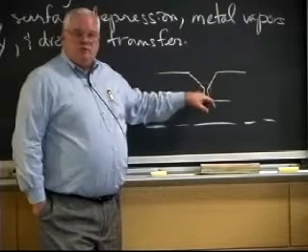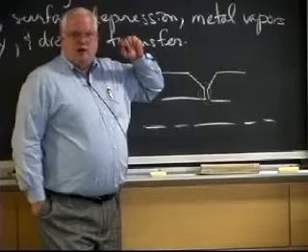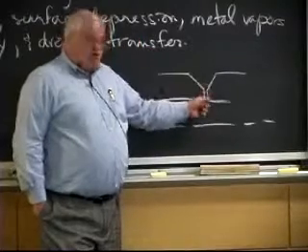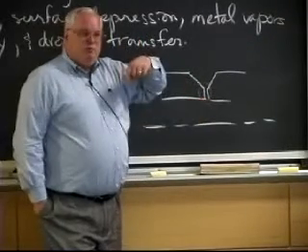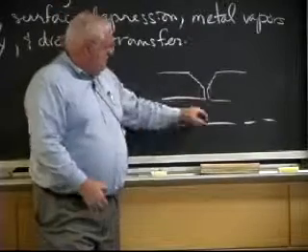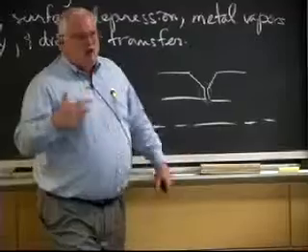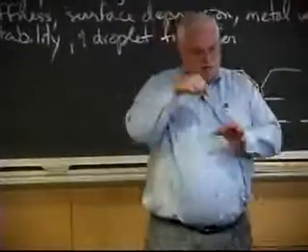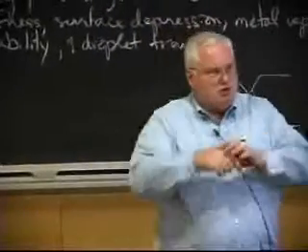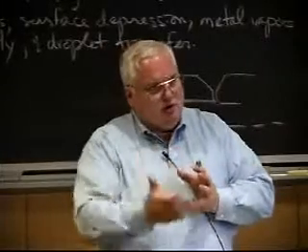The reason is that the root pass electrode is one that will have a strong plasma jet, and it will essentially punch a hole through here, and the metal comes around behind, and you get a nice underbead down here, because you're doing what we call keyhole welding. You drill a little keyhole, and you push things along, and the metal swirls around behind, and you get a nice underbead.